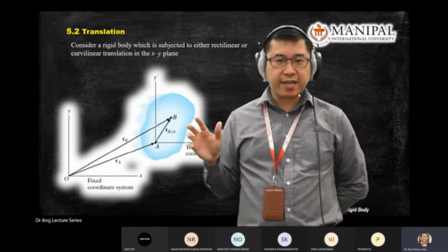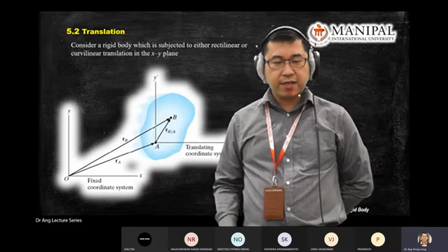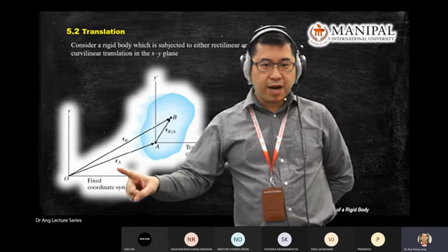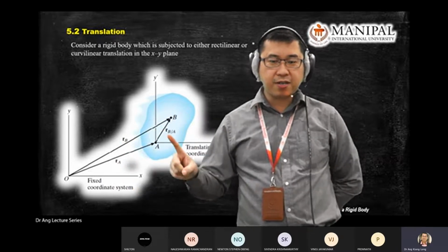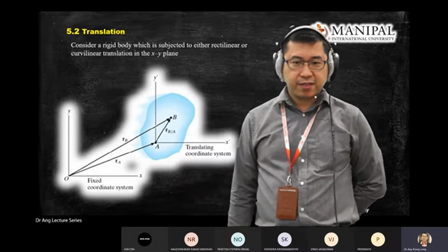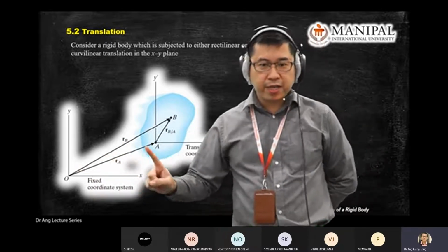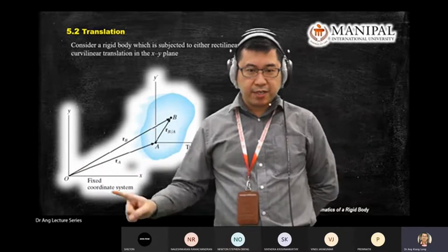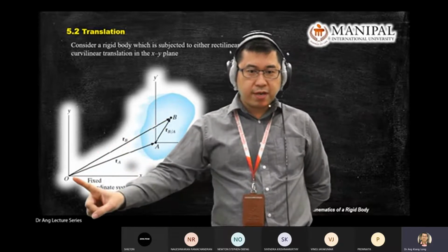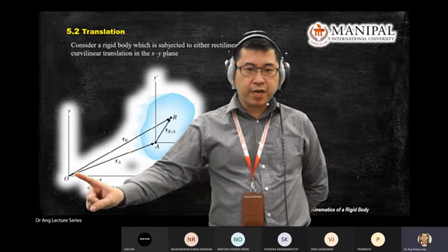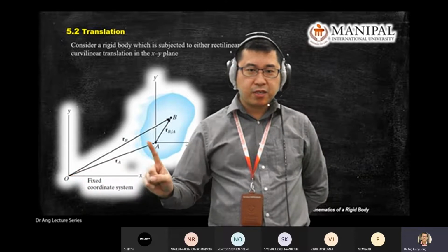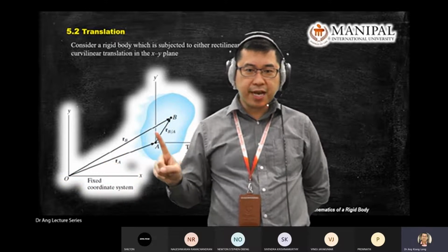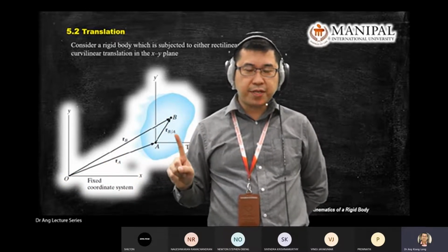So when you write the equation for the vector triangle, what can you write? RB equals RA plus R sub B stroke A. I repeat, all the arrows here are vectors. Recall your understanding of the vector triangle. You look at the arrows, how you form a triangle from the beginning to the end point consists of two vectors, RA plus this arrow. This arrow is RB stroke A.